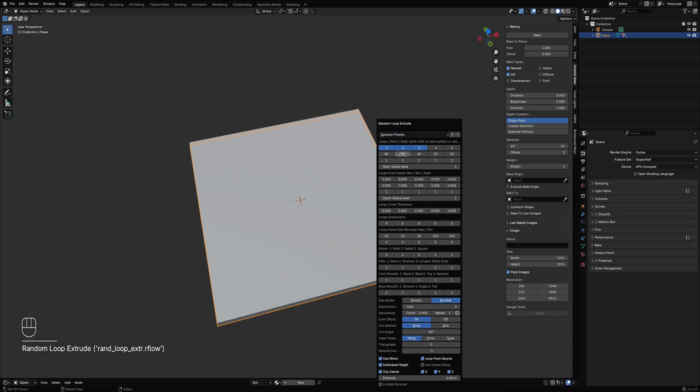This means that 3 loops are used, and with 80 ratio, it means that 80% of the selected faces will be used. That is from the source selection and when subdivided using the subdivision property here and also from here. So the resulting faces from that, 80% of that will be used for creating the panel islands.